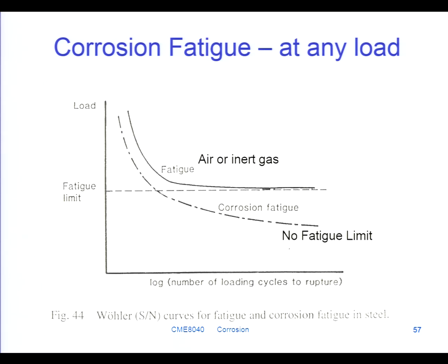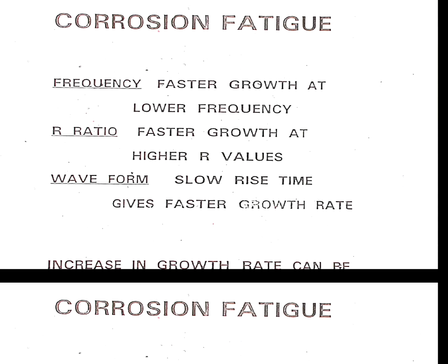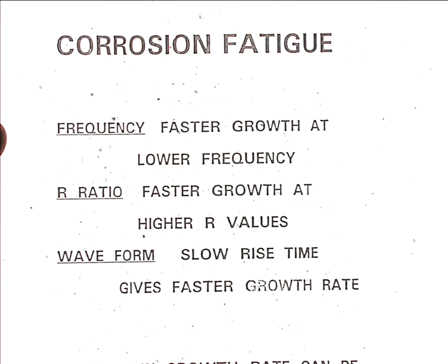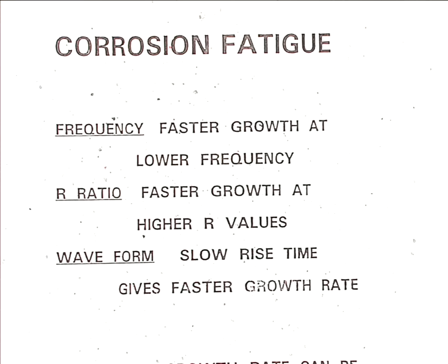You have to test for it at the correct frequency, at the correct loading level. You've had this one before as well, if you remember. Maybe. No. So you can't just do an accelerated test at a higher frequency. You can do that for air fatigue, for an inert environment, that's fine.